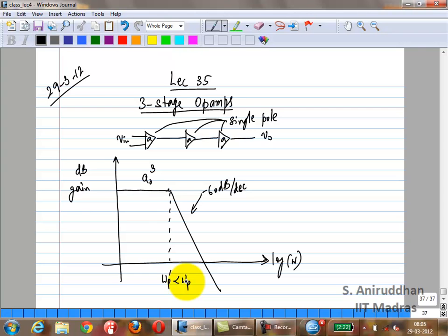What can you tell about the stability of the system if you place it in feedback? Let us say you have 3 gain stages which look like this. You place this in feedback. What is going to happen? Is it going to be stable or unstable? First of all. Unstable. Why? Yeah, so you want it to pass at minus 20 dB per decade. We already saw that, right?